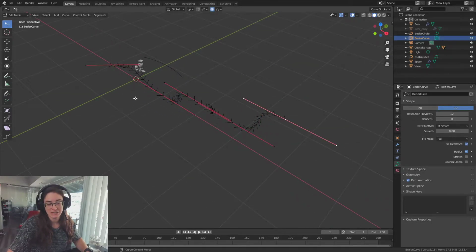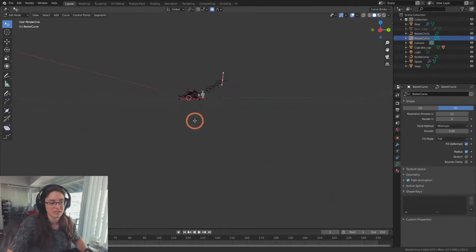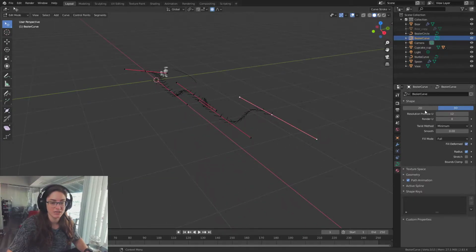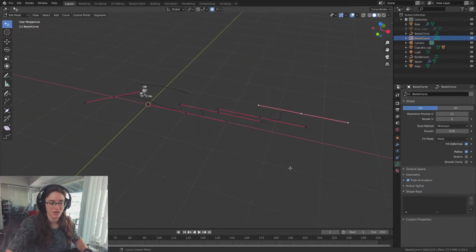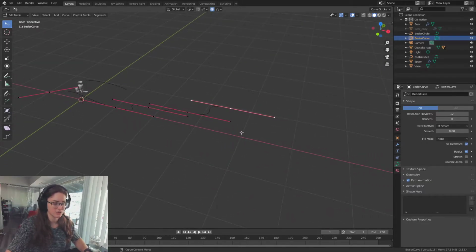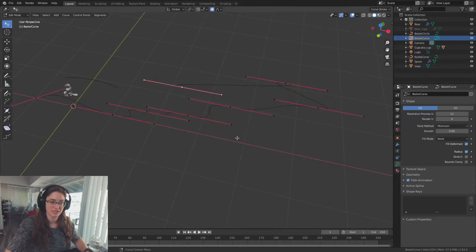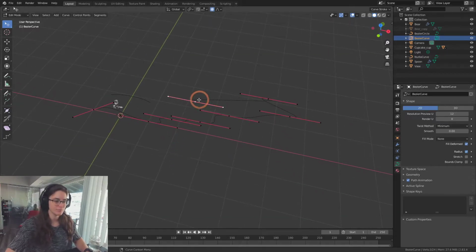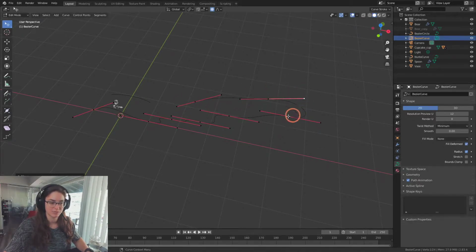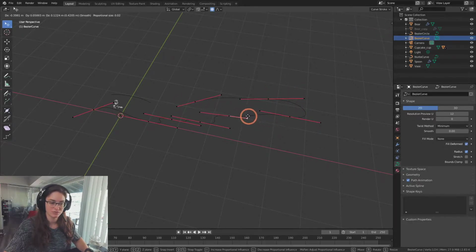And if you're placing it in perspective view and it's placing everything down 3D, you can hit the 2D button. And you can see all of my points that I just placed are now just along that flat YX plane. I can place some more points in, and they're all just in that 2D plane. So that is an option if you would prefer working in perspective rather than an orthographic view.